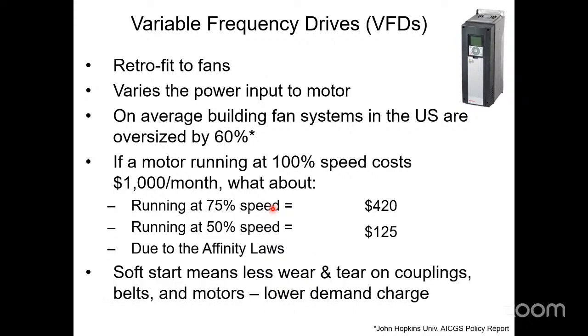VFDs also help out in terms of being a nice soft starter. They don't bang on. You don't hear ductwork expanding. You don't hear belts squealing. They ramp up slowly, so it does have less wear and tear on the motor and belts themselves. And you avoid demand charges if your building is having issues with that.